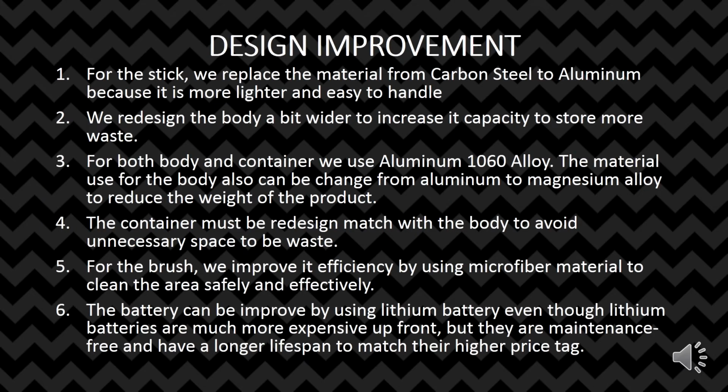For design improvement, after we have done the computer simulation for our product, we identified that we can improve our design to increase the efficiency and make the customer feel better when using it. Okay, for the first one, the stick. We can replace the material of the stick from carbon steel to aluminium, because aluminium is lighter and easier for the customer to handle.